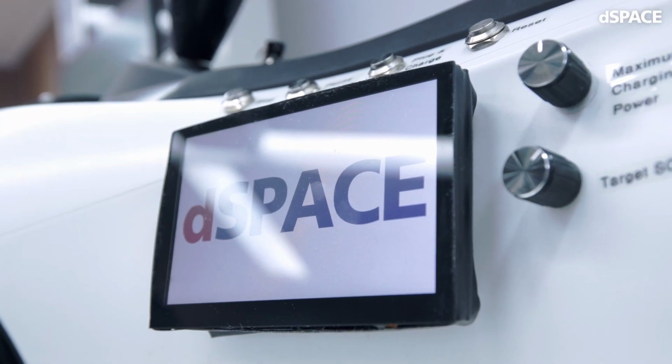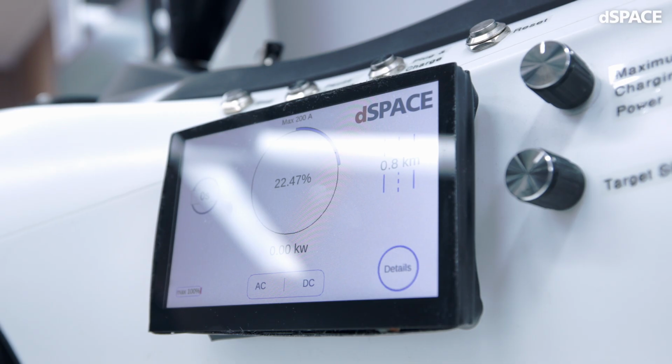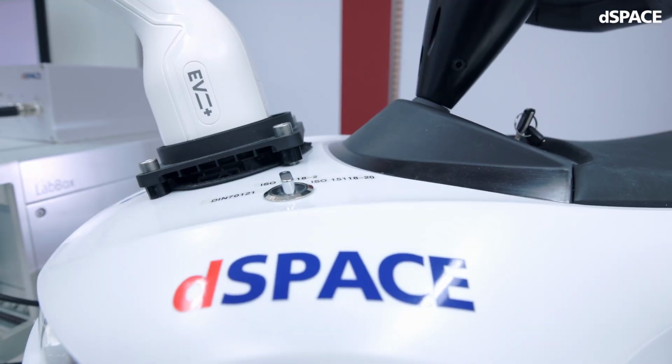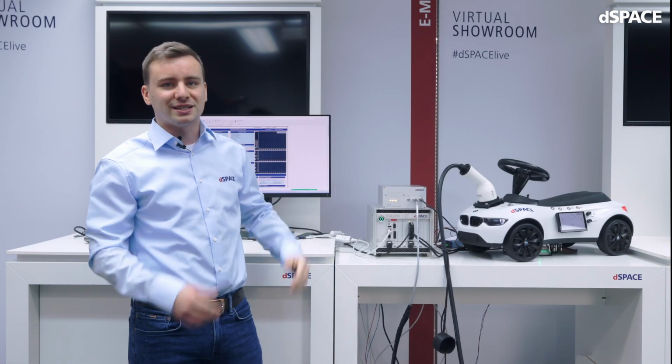Let's take some seconds. Now I just plug in the cable, and then, as we have seen in the presentation, at first the data link is established, the power line communication, then the TCP server is connected, and after that the whole charging process starts together with the battery data exchange protocol in parallel.